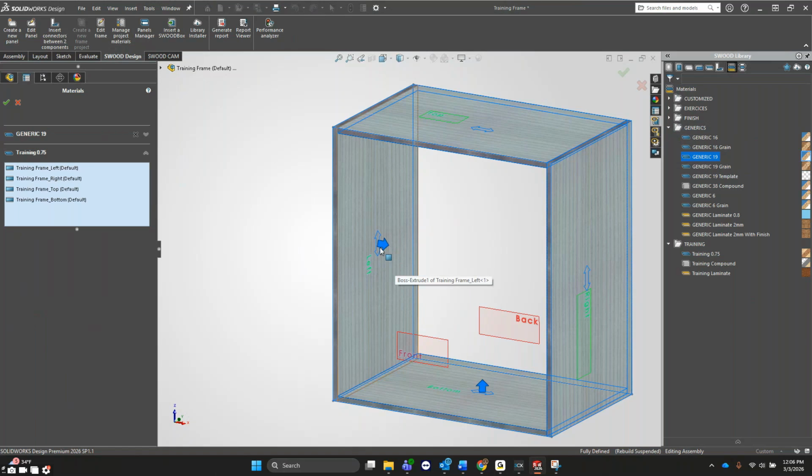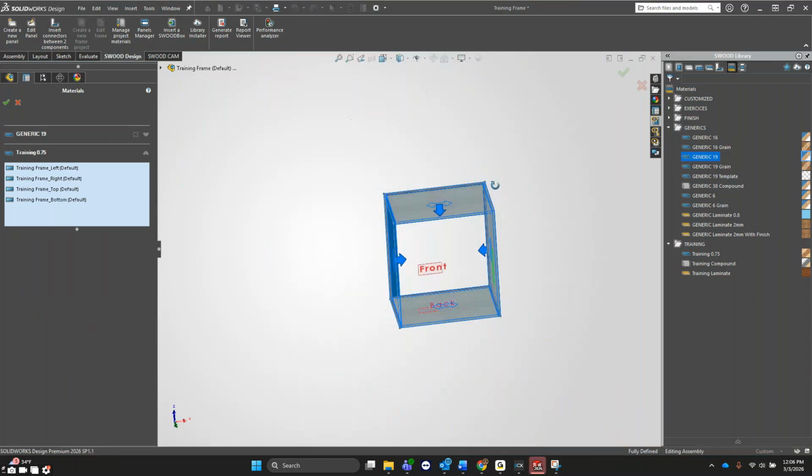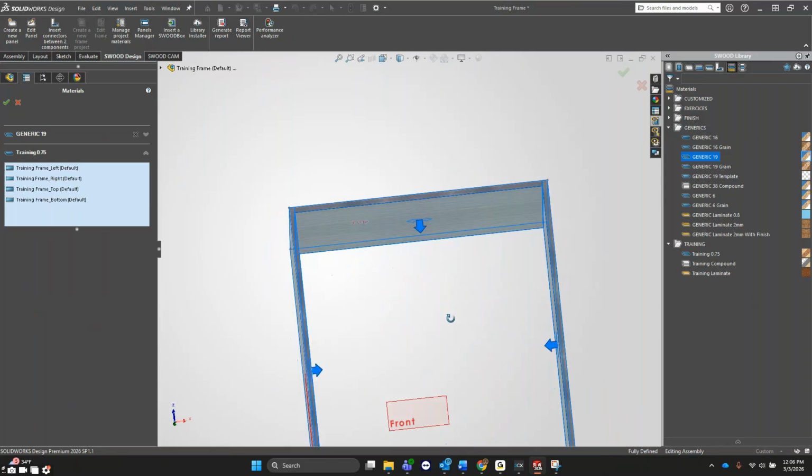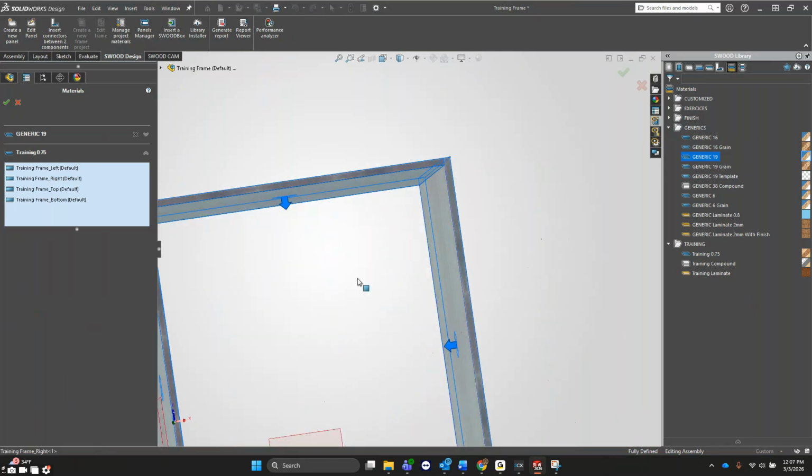they do it this way because they usually put the top where the most machining is going to be. So in a lot of cases, you'll have things like holes for hinges, line bores for adjustable shelves and things like that on the inside here. So they make this panel, this inside face here, the top, because that's where the most machining is usually going to be. So that's why it's laid out like that. Same thing with the other side, it's just mirrored, the top and the bottom.